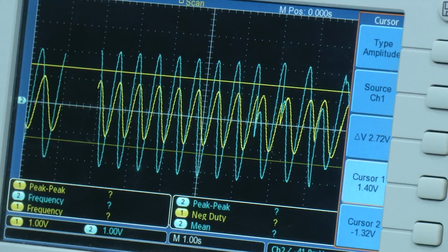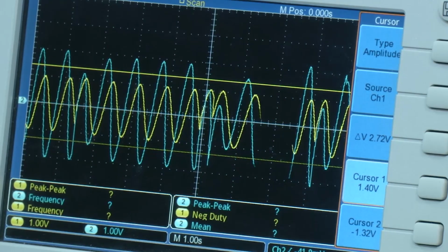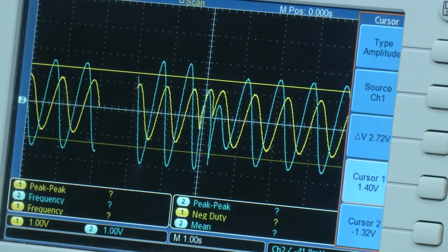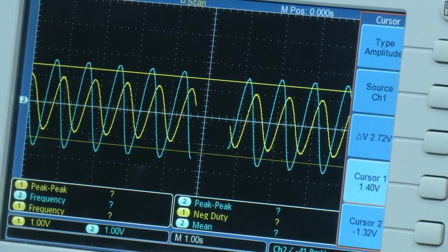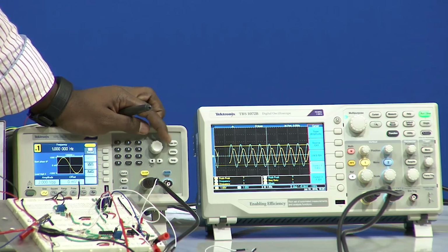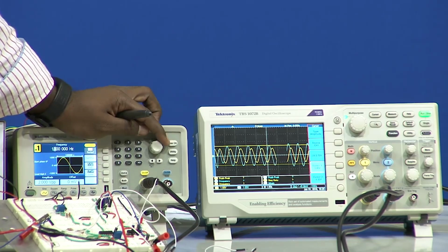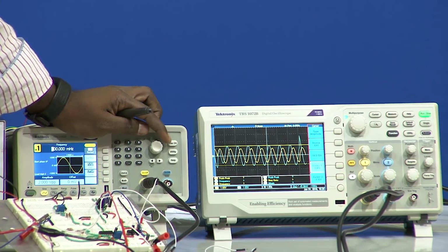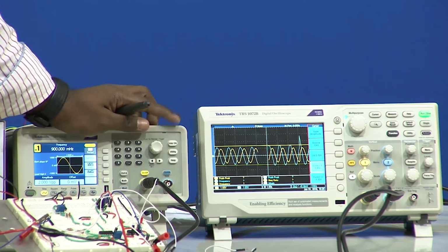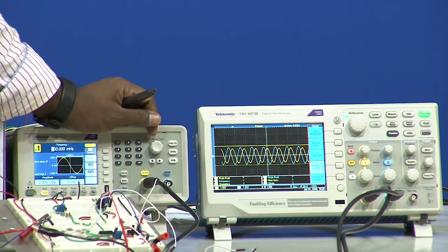Now, we will observe at what frequency. Right now it is 1.3, now I am setting it at 1.1. Even at 1.1 hertz the output value is higher than the cutoff value, the cursor point which is at 1.4. Slowly I will decrease to 1 hertz. Now, suddenly it has moved to the 1.4 volts 3 dB line. Now, I will slowly decrease, and we can see the output is below that cutoff. When I zoom into the oscilloscope, we can observe that the output is below the cutoff.